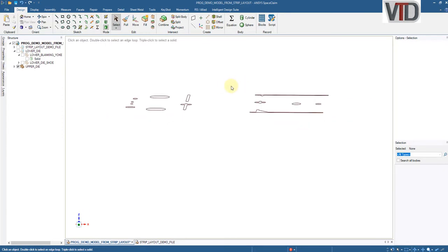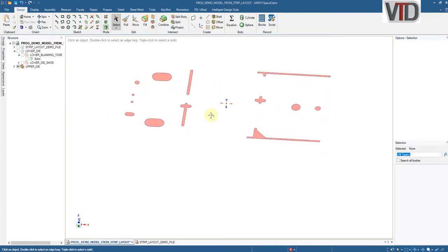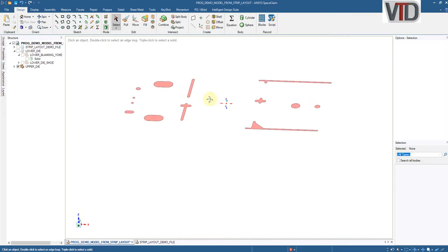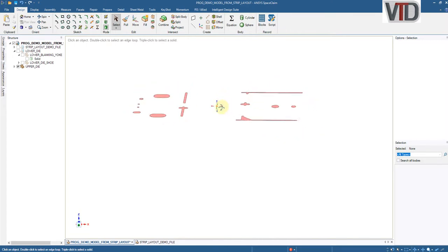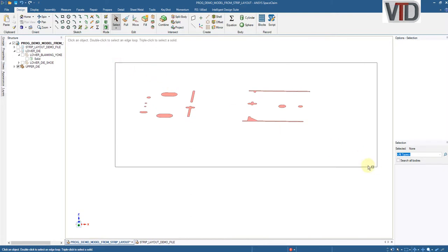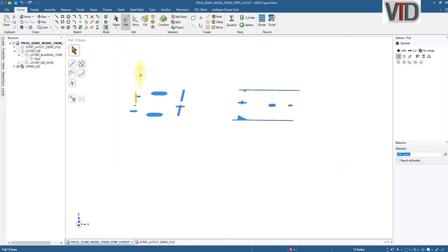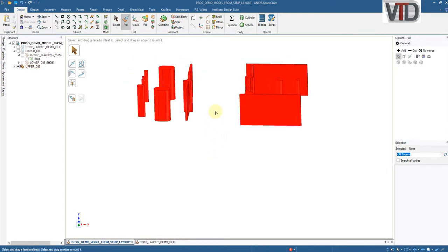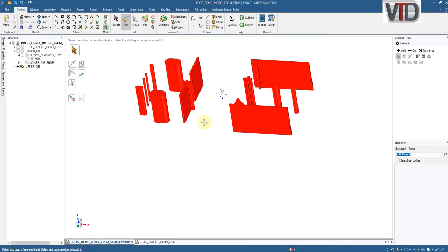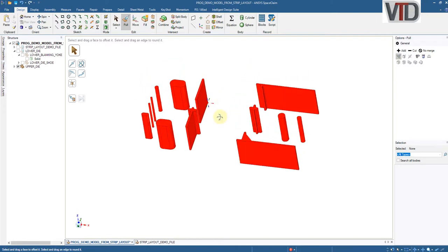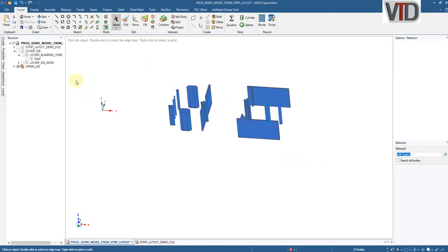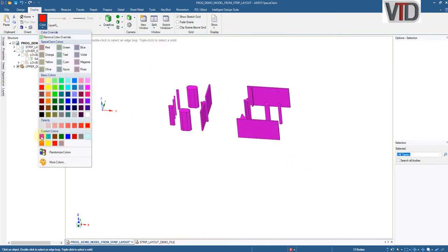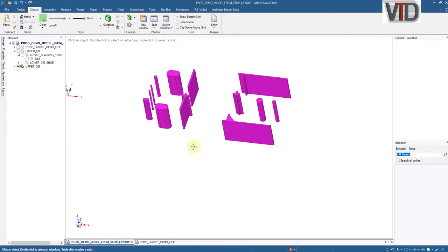Okay, with my strip turned off, now I've got these shaded, these are basically the top surfaces of the trim. And what I can do with these now is I can window them and pull. And I want my upper trims to be 100 millimeters. So I can punch in 100 millimeters. It recognizes the mm as a metric dimension when I punch it in, even though we're working in inches. And now I can window this entire thing, and set the color to my A2 tool steel.